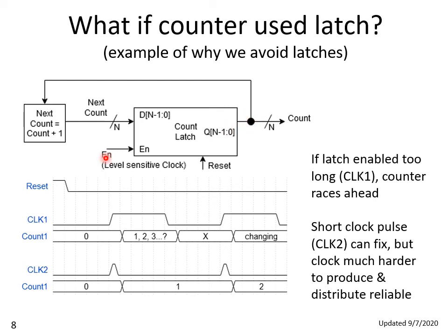So depending on the duration of the clock signal, this could end up giving you unpredictable results. For one thing, the speed of real circuitry is not completely consistent. The delays of the circuitry will vary with temperature, with variations during the manufacturing. It can be affected by noise in the environment.